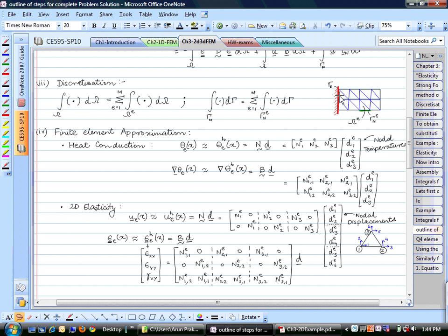The idea is that you go to each element, you plot the value of the temperature at each of its nodes using this patch command, and there is an option in this patch command to use interpolated color. So it will generate a color plot of this entire domain for the temperature problem, where you can see how the temperature is varying across your domain.